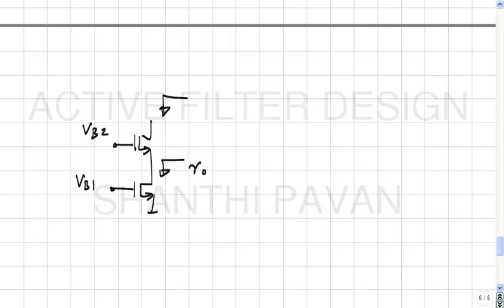Both the transistors will have the same RO. Right? But that doesn't mean the output impedance looking in here. We are looking at the incremental impedance from here. When we say RO, we are looking at the impedance between that node and ground. Is this clear, people? Alright, how do you find the output impedance now? Incremental equivalent circuit, what might that be?